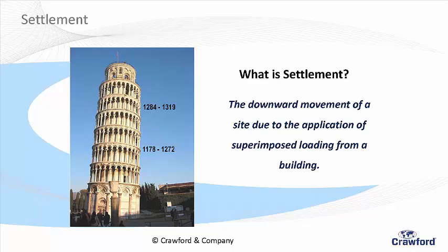But it is the weight of the building. So you're right, it is predominantly new build, but also where they've changed loadings in the building. Loft conversions, could be putting in lintels which are undersized, or pads which aren't in the right place, or haven't got the right kind of material. If you change the load distribution in the building, you often put point loads in areas which may not be designed for point loads. Then you may have downward movement. Okay?